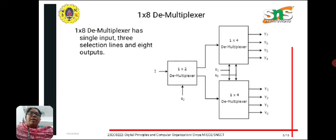This is an example of a 1 cross 8 demultiplexer. It has a single input, three select lines and eight output lines. For a 1 cross 8 demultiplexer, we have three select lines. For a multiplexer also we have three select lines, and for a demultiplexer also we have three select lines. But in a multiplexer we have 8 input lines, whereas in a demultiplexer we have a single input line and 8 output lines.